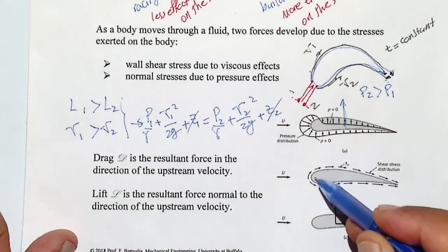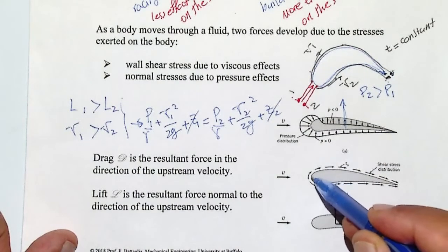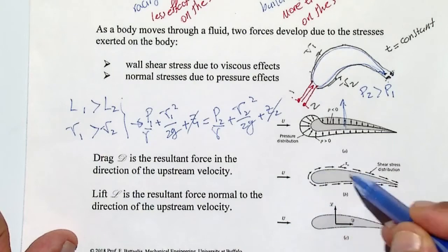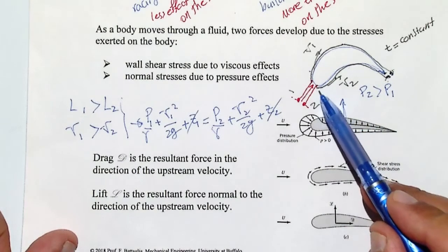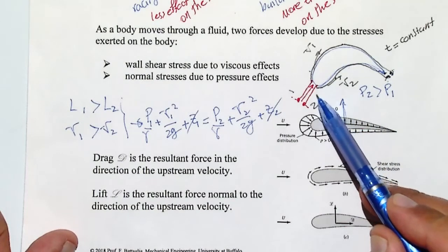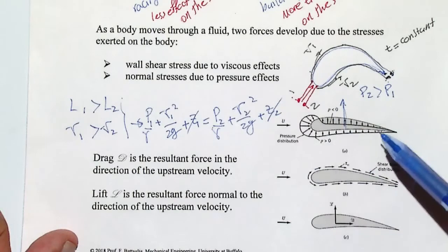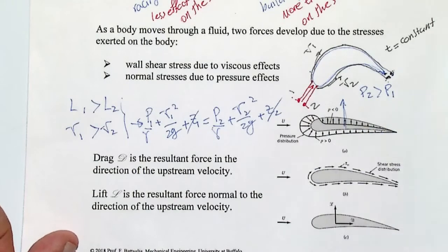That means the flow is so fast that the tau, or shear stress, happens but very close to the wall. So you can apply Bernoulli where you have no shear stress around the object, in the uniform flow around it, where you don't have any losses of energy because of the boundary layer.